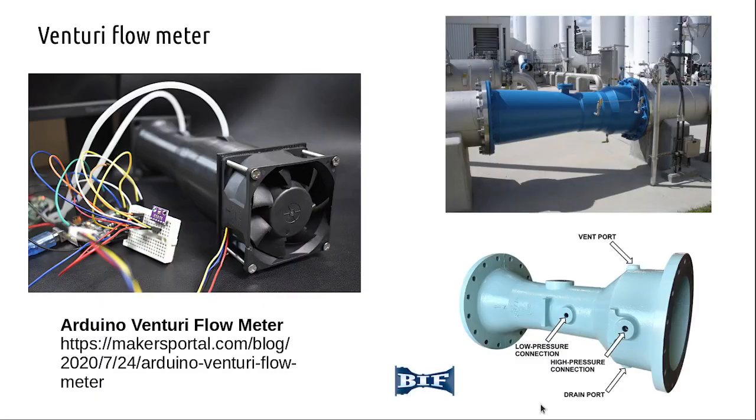So this is a particular Venturi meter which is installed in a pipeline in an industry. You see the typical thing, and there is a tapping there, vent holes. So you are recording the pressure at these 2 points and transmitting it. You have the low pressure connection, that is P2, and this is the high pressure connection, P1.